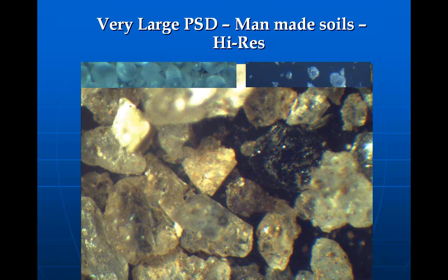But let me say this: the variability is still so great. It's in the materials that are used. I always tell the story of compare a 1-acre dentist office to a 1-acre gas convenience operation. The material that comes off of them is not going to be the same. The amount of organics is not going to be the same, and certainly the traffic rates. 1,000 trips a day to the gas convenience store, maybe 10, 20 to the dentist office. All of these things go into what is coming to a BMP. Now, since I'm in the manufacturing business, I tend to think of things in that way, but it's just as important if you're designing a sand filter to think about whether or not you need to protect it and how much in the way of small material is going to come to it, how quickly a pond's going to fill.